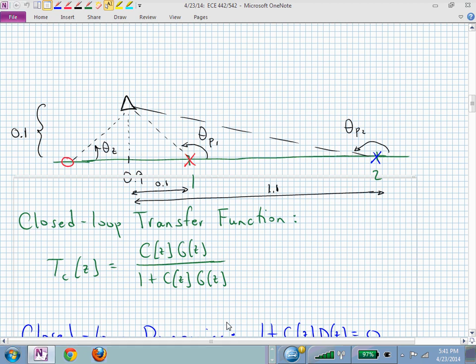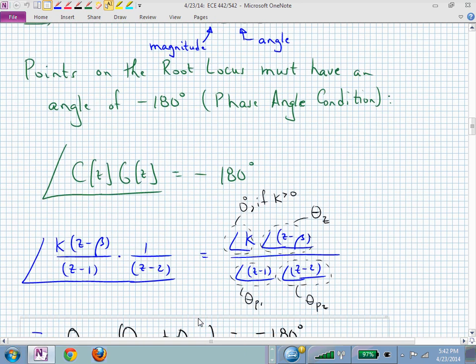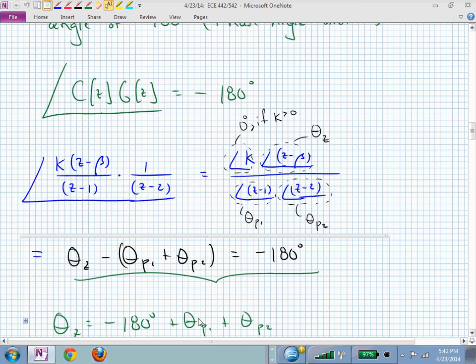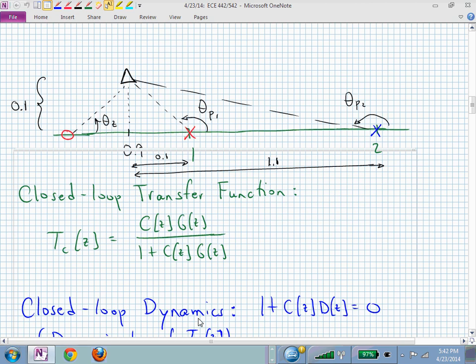Is it clear the kind of thinking or processing you need to be doing for this design approach? This is just a PI controller. And what we have available to adjust is that 0 location. That's what we're adjusting.